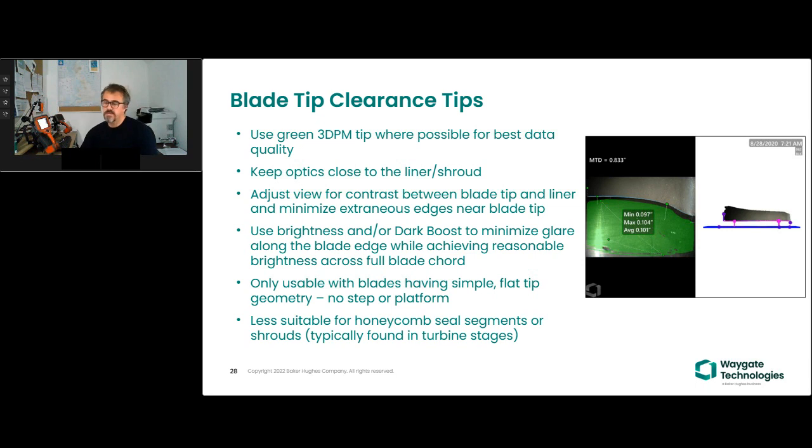So, for instance, the CFM56-7B turbine, I do know that doesn't have a honeycomb seal segment from the trailing edge, and you can, so it does work in the turbine as well. But yes, really tuned for the compressor set of blades. Again, blade tip clearance is a measure of sort of compressor health.